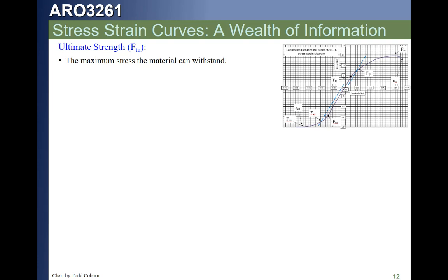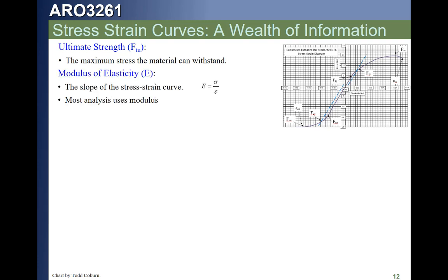You'll notice we could talk about the modulus other places. Let's do that for a minute. We said that the modulus E is just this slope here, right? But actually at this stress up here, we've got a different modulus, and at this stress here, we've got a different modulus. That's called the tangent modulus, which is given a subscript T, not because it's tension, but because it's tangent to the curve. You could also talk about the tangent modulus for compression, okay?